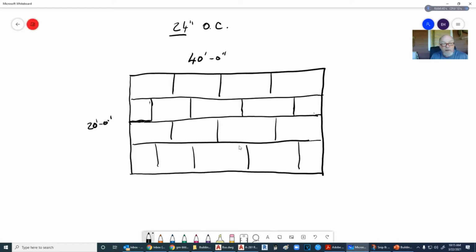Well, guess what? Right here, we've got 4 sheets. We took half of it over here and half of it over here. Back to four full sheets. And then we're going to use the half and the half here. All right. So when we're designing that house, really, we need to be looking at a half sheet of plywood.